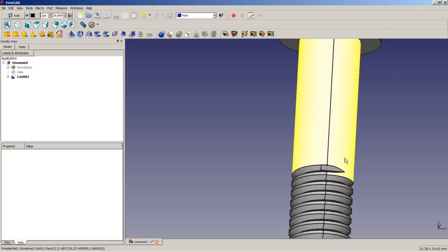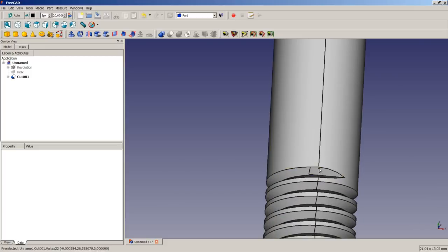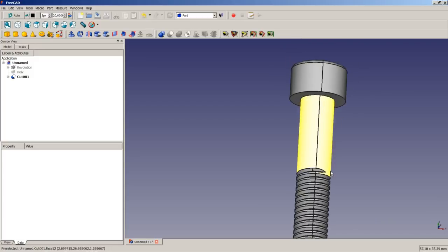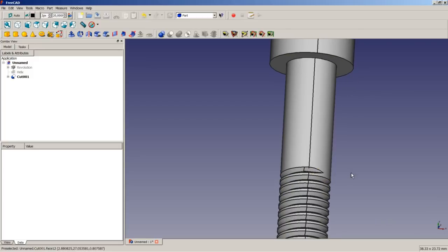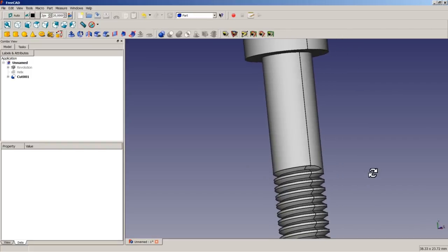So as you can see, sometimes we have to cheat because FreeCAD is quite weak on helix-based operations. You may succeed with older or newer FreeCAD versions. It is sometimes a question maybe of a little bit of luck, and sometimes you have cases with a good relationship between your geometry constraints, and sometimes a bad relationship between your constraints, leaving the basic core unable to perform the requested operation.